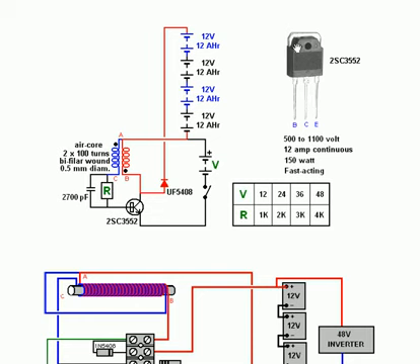The transistor itself operates very simply in a joule thief circuit. It operates on a coil which you wind yourself. The coil is air core, which means that it's just wound on an open former, something like the cardboard center roll of a roll of kitchen towels. It's made of two separate strands of wire, one shown in red, one shown in blue here in this diagram.